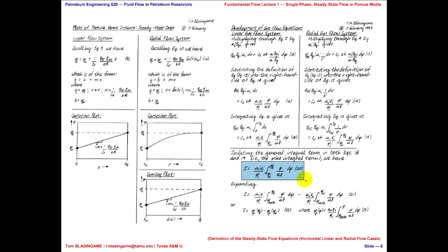Why are we stuck with that stupid equation, as I just said? Now, your generation doesn't care about this because it's all in the software. But my generation had to care about it. Because what are the units of that integral I? It's P for pressure. Everything else cancels. Why is that important? Because if we'd have used that form, we would have ended up with exactly the liquid flow equation, only we would have used a different definition of pseudopressure.